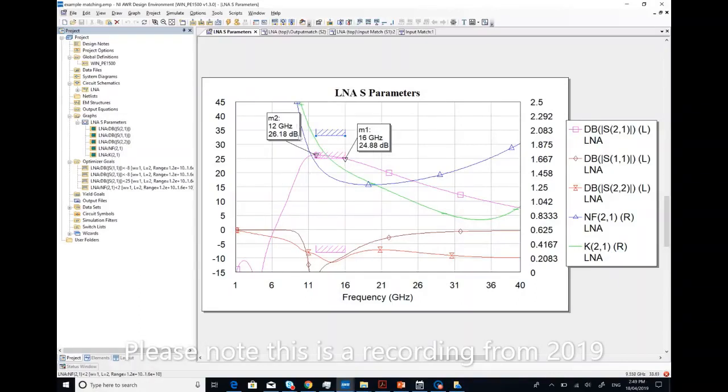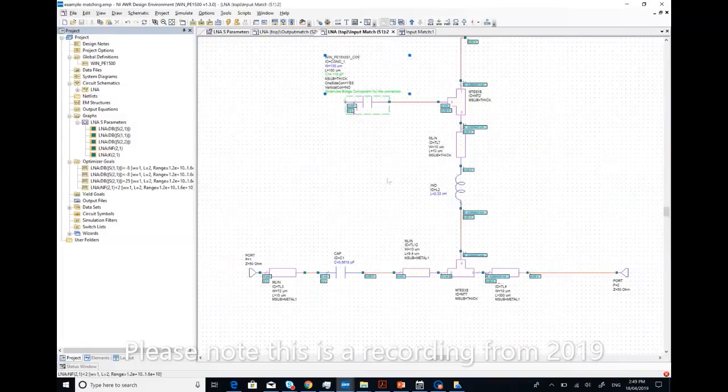Now let's say this is sort of the final circuit simulations. Now the problem is, let's say we're satisfied with this circuit simulation. If I go back to my input match, I have capacitors and inductors, ideal ones. Now how do I make them on a circuit, because I'm not going to wind a coil to make a 0.33 nanohenry. So on a layout you can't have a coil, you have to have it in a microstrip line. Now specifically targeting review 2, you don't want to have these ones as your final. You will need to have them in a microstrip like the MLIN version at least.